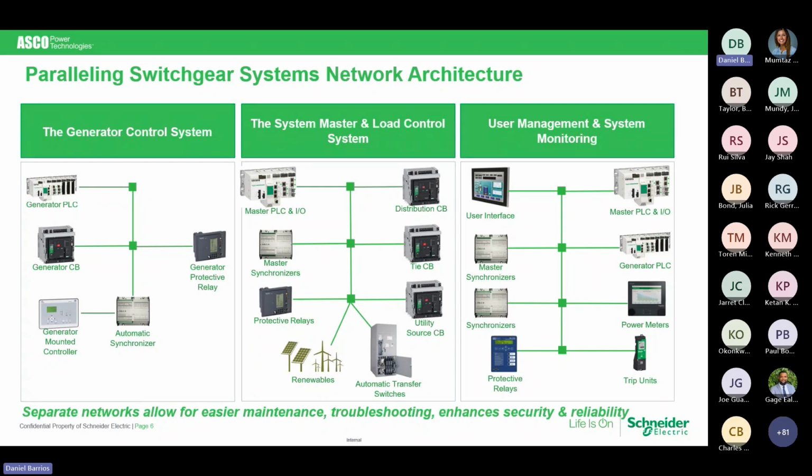The generator breaker is included, obviously protective relays. You're going to see a lot of the generator mounted controller. And then what you're looking at in that first left-hand side is a Woodward DSLC, digital synchronizer and load control. When we are doing that, we are taking the responsibility. We are sending a bias signal to your generator set controller for voltage and for frequency, raise lower.